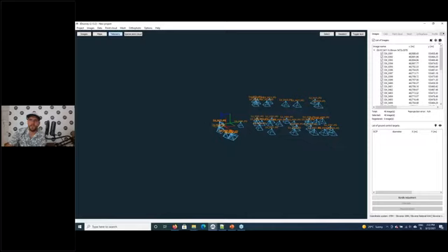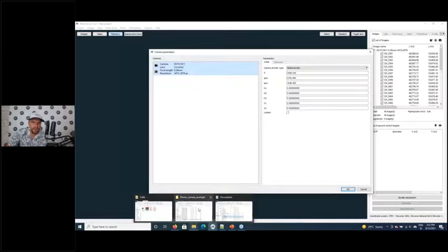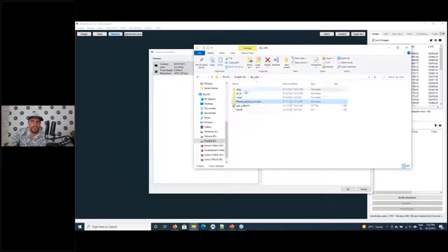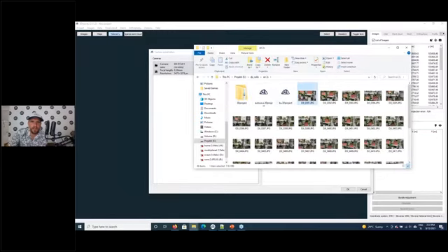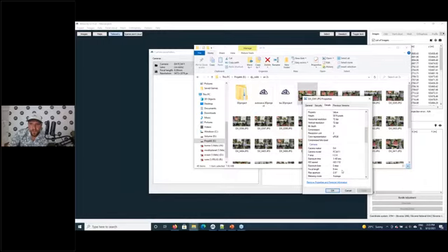Right, now let's check the camera parameters. Because this drone is not in our database yet, our initial camera parameters are calculated out of the data in the pictures. In the pictures themselves, we have here already the focal length in millimeters, but you see it says 8 millimeters.